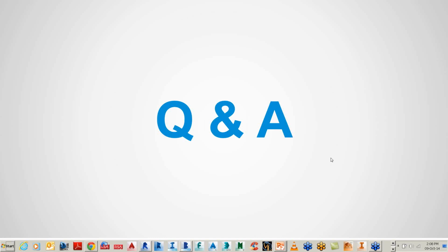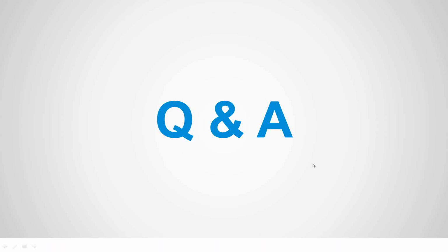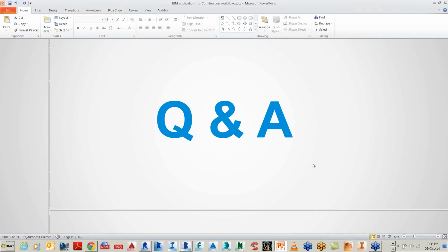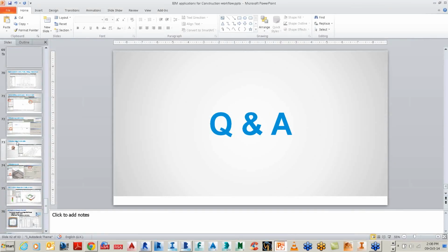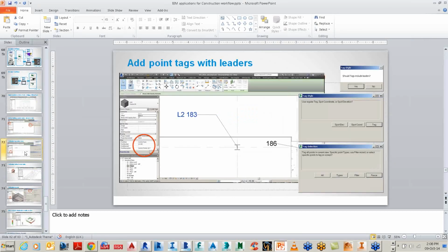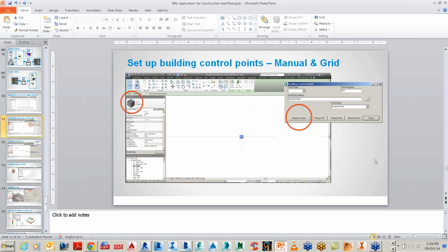We do have a specialist in our office who could probably explain this in more detail, but in essence, you can put points anywhere within your model and set them up to different locations, and you can do penetrations in the slab if you want, and then go out, set them out, put in your formwork, and then record that information, then take that back into your Revit data and see if the opening in that slab is being set out in the right location.